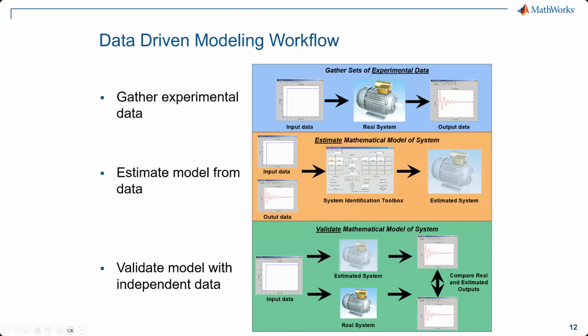A transfer function means some kind of equation which will help me relate the input data to the output data. And once that is done, I will also do one experiment: I model that equation, maybe in some simulation tool like MATLAB and Simulink, and then I try to compare whether the output of the simulation data, that is the estimated system, and the actual system are matching or not. This is a very simplistic way of doing it, where we are doing some experiment. An experiment is like taking a real system, just like we do in a lab. We give it some kind of input and capture the output, and utilize that same information to find the transfer function or model it. That is way number one.